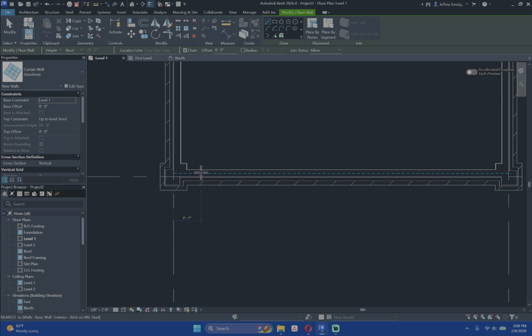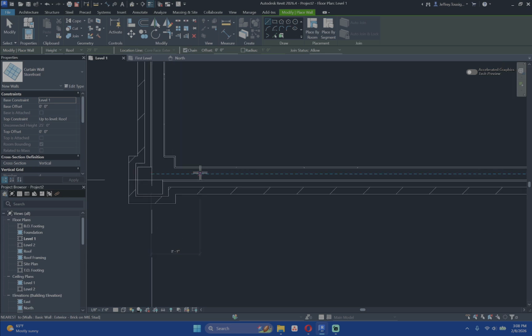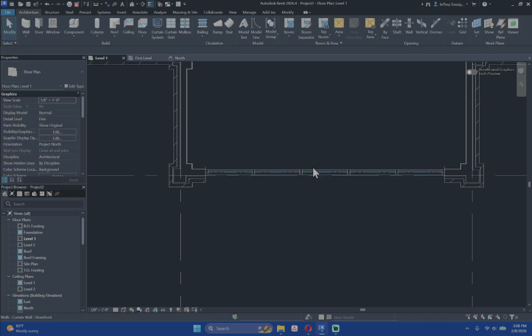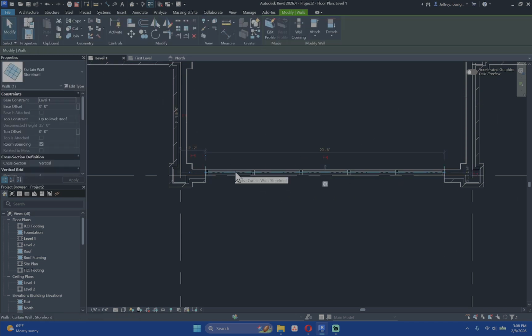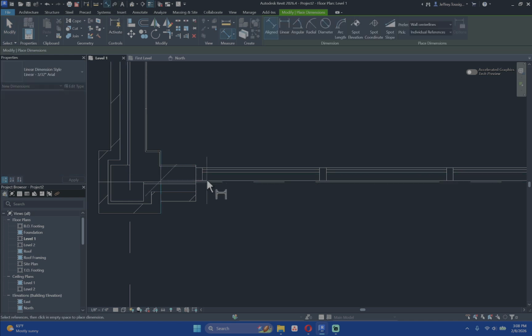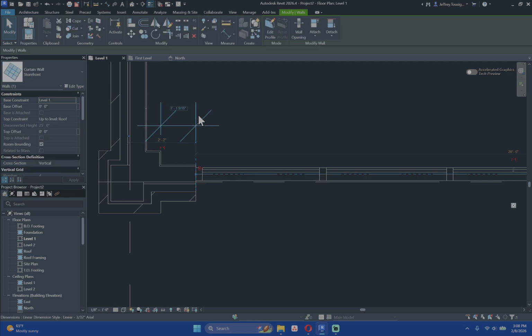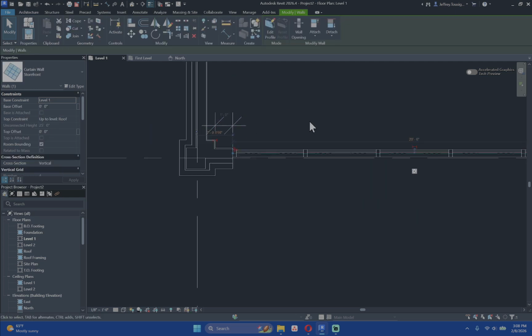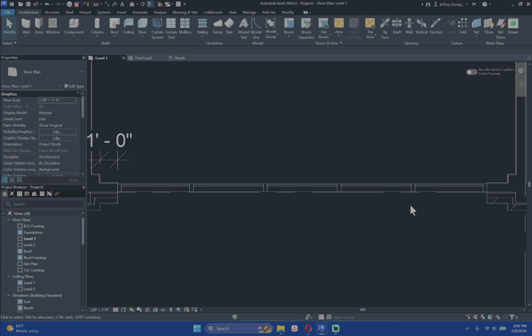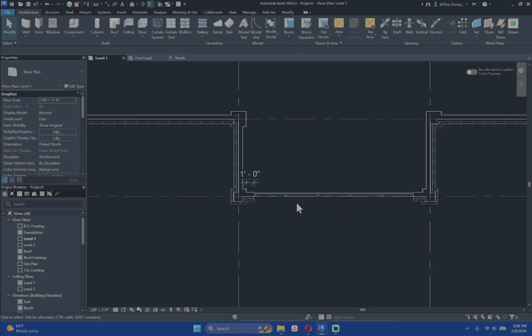And we're going to draw it on the stud of the exterior wall from one side to the other. Now, again, if we knew exactly where this needed to be placed, you can use temporary or permanent dimensions to locate that curtain wall exactly where it's needing to go. But I'm not going to do a lot of heavy designing in this because we just aren't there yet. So I'm just going to leave that there.